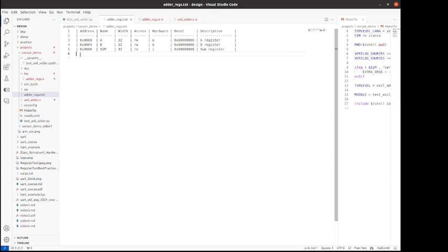So let us define one more control register, which is 1 bit wide, which will tell the start. We are defining access such that software will come and set this bit, and hardware will acknowledge this start, then it will be cleared by the hardware. So that's what this RW1 is. So from the CSR, the hardware will have one output and one clear input.